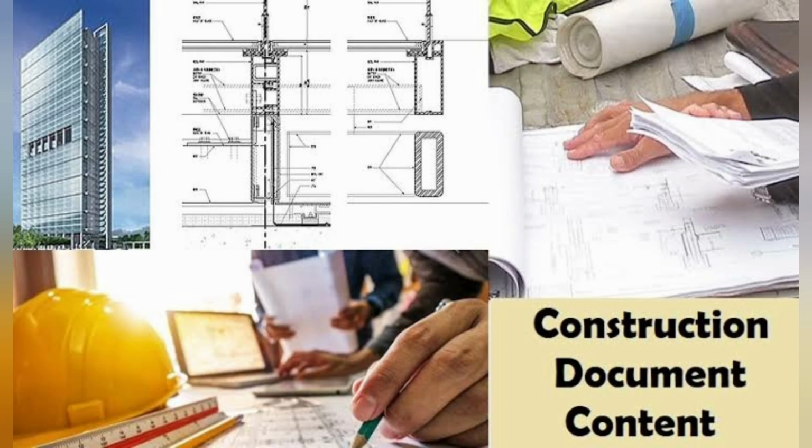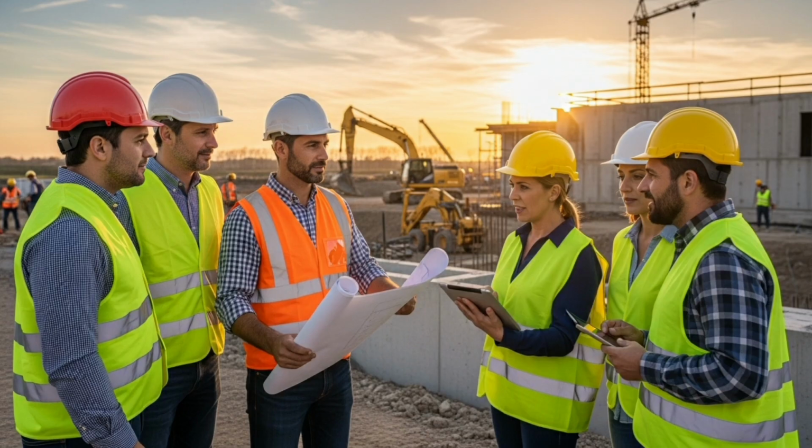Mark up your own set of drawings with as-built conditions and take photos. Your meticulously maintained site diary and marked-up drawings are your only protection in a dispute. This proactive, questioning approach is what transforms a junior engineer into an indispensable project leader.